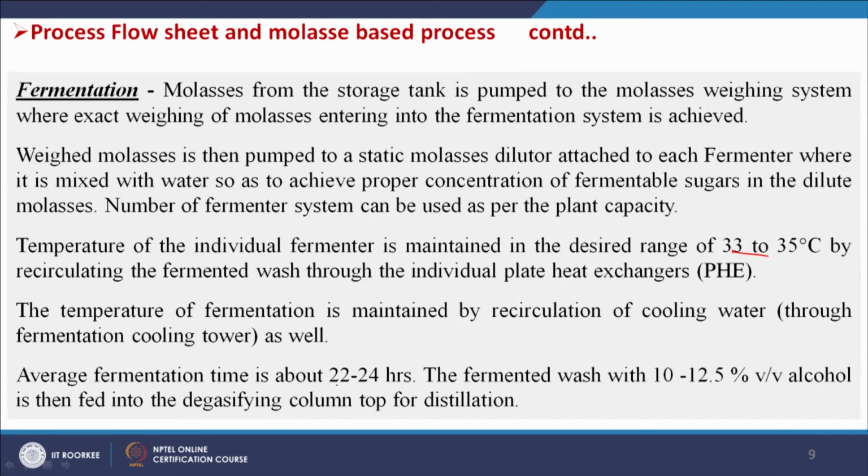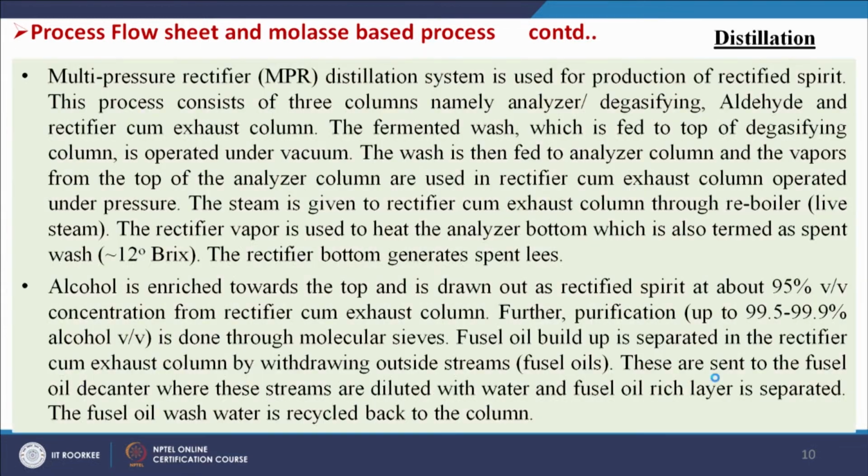Temperature is maintained at 33 to 35 degree centigrade, and the average fermentation time is 22 to 24 hours, and after this fermentation the fermented wash contains 10 to 12.5% of alcohol. So, this is the fermentation unit, and then the distillation unit.